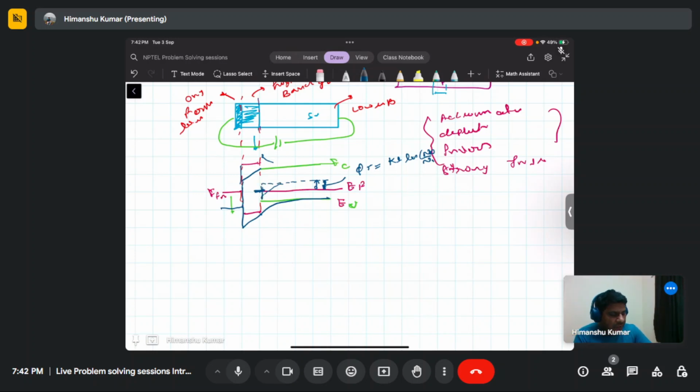At the interface, EI will become lower compared to EF. So we can say the inversion has taken place, and the interface has changed from p type to n type, or n type to p type.